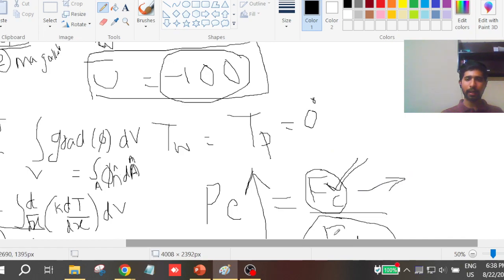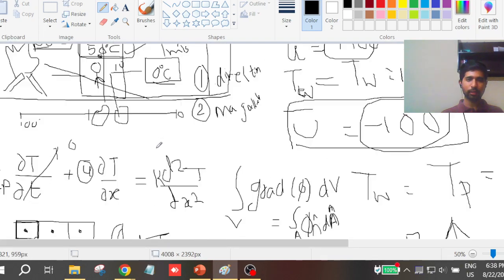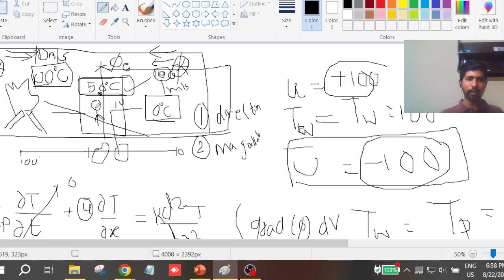In technical terms, I had just directly told you that here you substitute directly the temperature of fire, or you directly substitute the temperature of the ice block. That is particularly called the upwinding scheme, and what I had told you here is actually first order upwind. I think in your content, second order upwind and others were present.